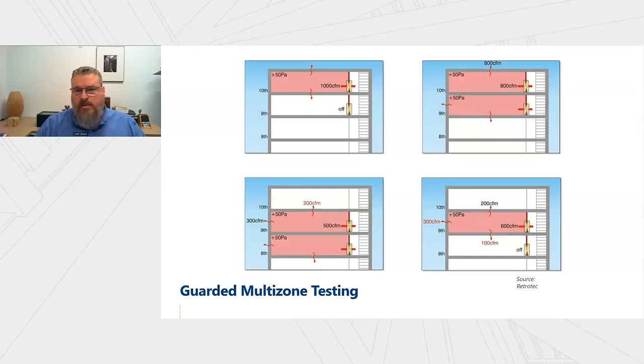And so the way you do that: for air leakage, you have to have 3 things. You have to have air, you have to have an opening, and you have to have a pressure differential across the opening. If you get rid of any one of those 3 things, you don't have air leakage. So we can't really get rid of the air.